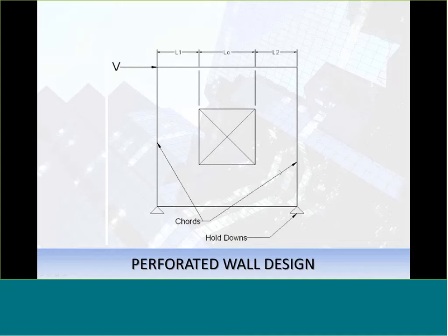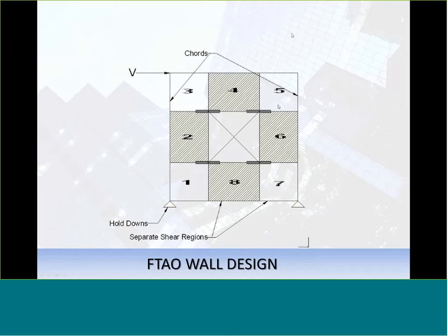So when you're perforated, it's a nice hand calc method, and you can really get back to that using your NDS calcs. And we show you that all in the detail report. It's a nice way to see it, but it's a little more based on theory versus what's happening on each strip or segment, what we call that. So we've got that perforated wall design method, and then the last one is the force transfer around openings, which is sort of a blend of the two.